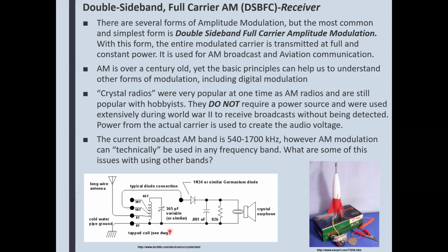Well, the same thing goes the other way. If it's tuned to have a little, because you're talking milliwatts here. You're talking really, really small amount of wattage that the antenna is receiving, but it's still enough to create a certain type of voltage or electromagnetic variation within the antenna, to create voltage that can be picked up by the tank circuit.